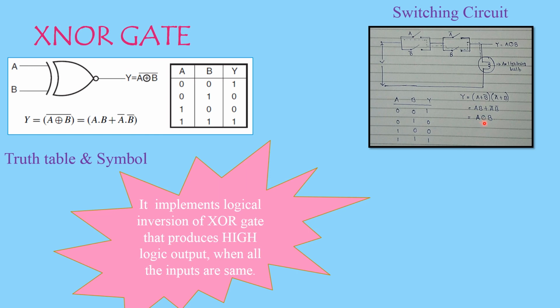And also remember, you can also rewrite this expression, that is inversion of your XOR, like this, with a dot encircled. So this is also the dot encircled symbol, called your XNOR operator. So remember this expression. As I've told you, only these two combinations would contribute to your high output. Whenever A and B switches are closed, you will have the lamp glowing.